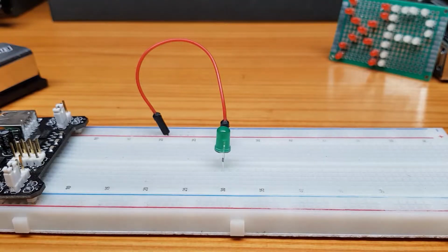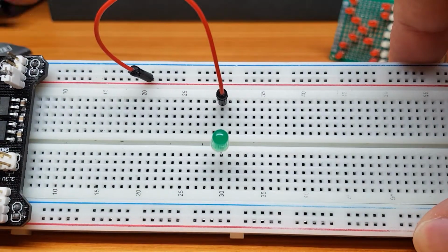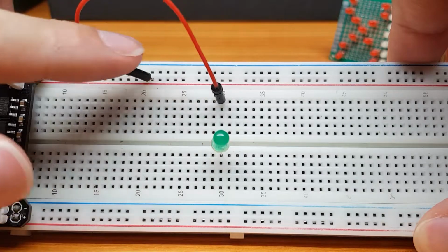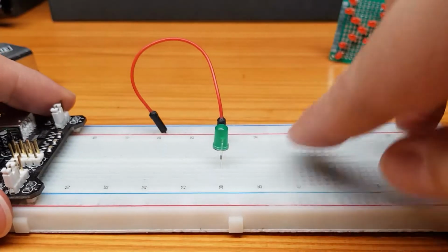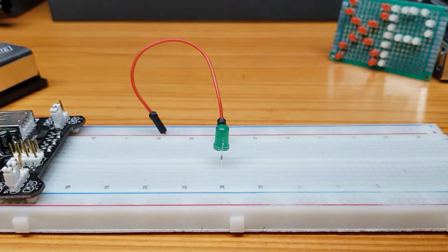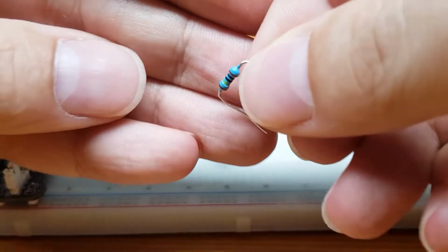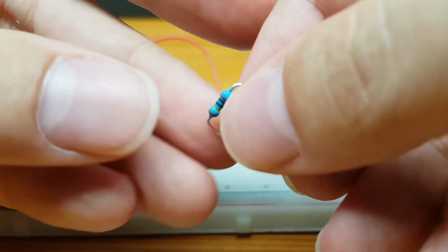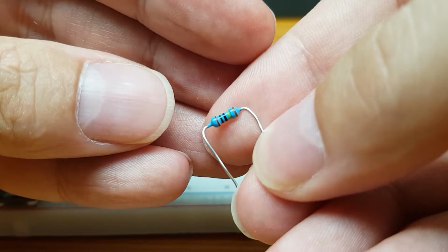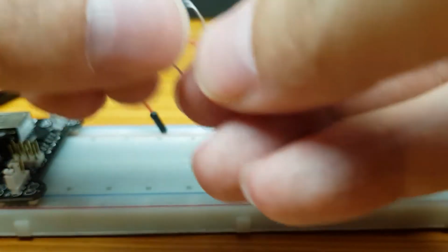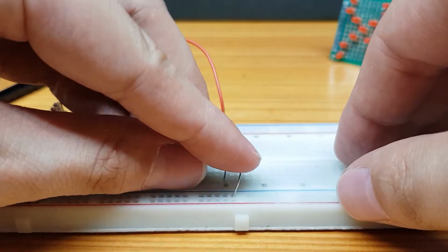Okay, so I have a little breadboard circuit here. It's not a complete circuit, obviously. You can see the LED is just connected to the positive power rail of our little power supply, and we're going to connect it to the negative rail using a resistor. The first resistor I have is this one here. If you remember your resistor color codes, you'll be able to see if I have it the right way around. This is a 1 million ohm resistor, or a 1 meg ohm resistor. So let's stick that into the circuit to connect it to the negative rail.